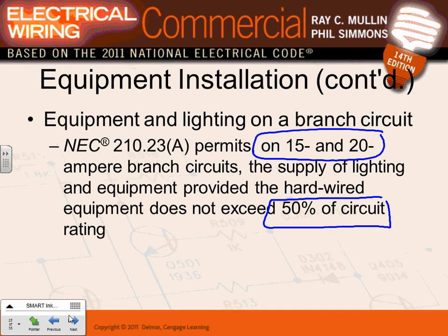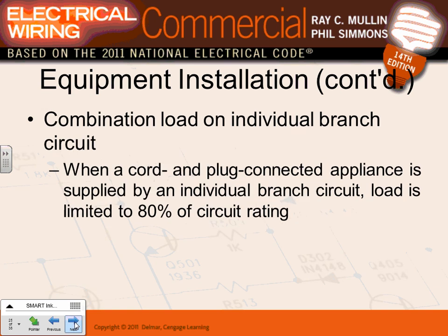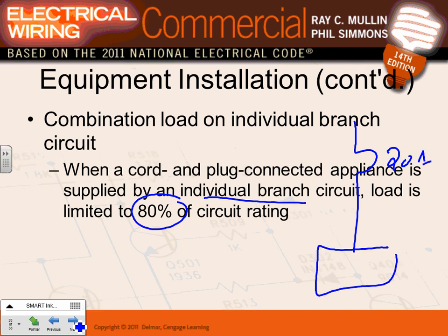If it's a dedicated circuit, it's rated for what? 80%. So remember that one. So why in commercial industrial, guys, that's why we always give a dedicated circuit. You have a dedicated circuit, plugged in or hardwired, individual branch circuit, you can load it up to 80%. Who cares? I have a 20 amp dedicated circuit to a machine here, 3-phase. That machine I can feed 16 amps on that. That's 80%. So if my machine is 16 amps or less, I'm covered.